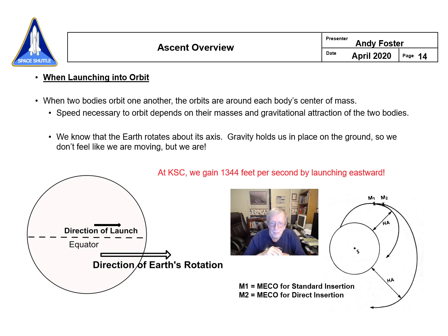Now we had two types of orbits that we would fly into, and two ways of getting there. When we first started off the program, we had a little more conservatism in the system, getting used to everything, and so we used a technique called standard insertion. In other words, we flew up to an orbital target and we didn't go as fast as we possibly could.